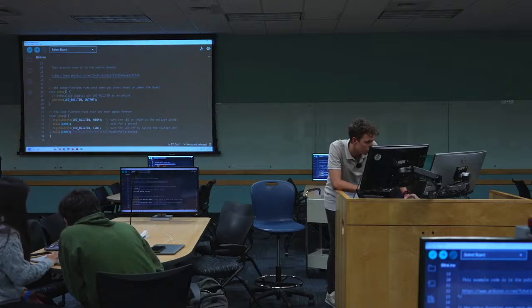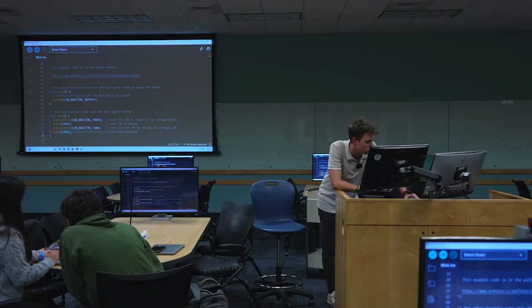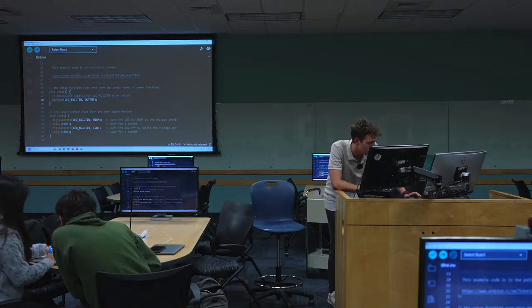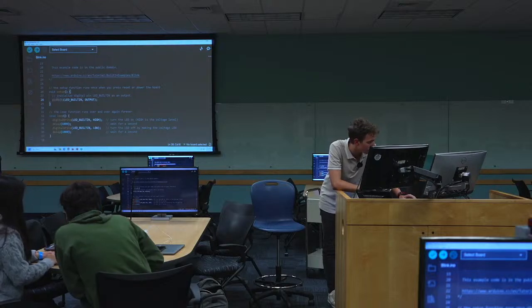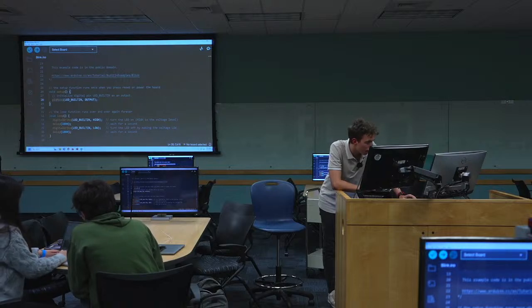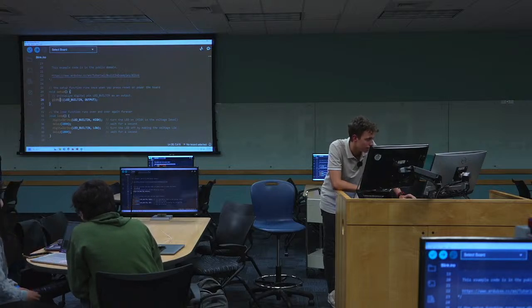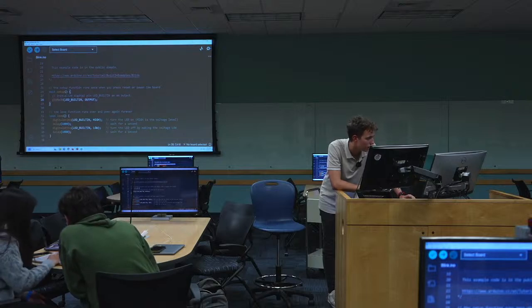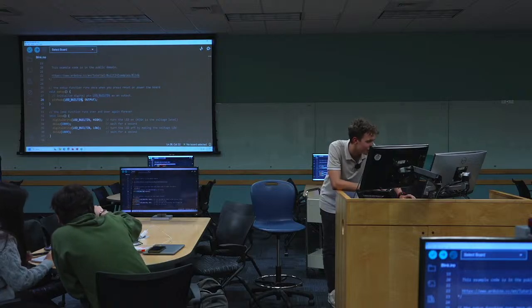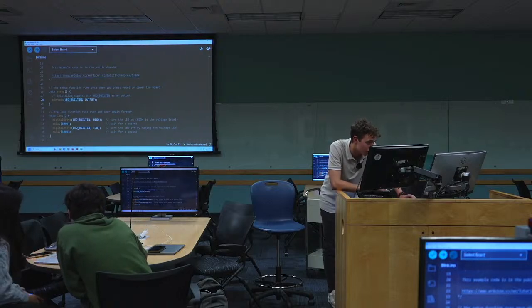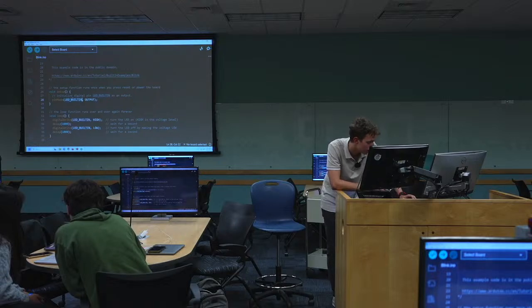So we're going to be using pinMode. If you know about programming, you can see that we are calling a built-in function in Arduino, pinMode, and you pass two parameters. The first one is an integer, a number, and in this case it's LED_BUILTIN, because Arduino has its own functions like these and variables that we can use to get started more easily.